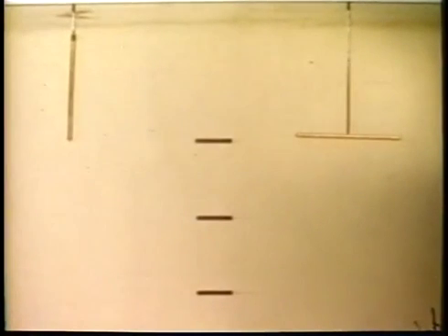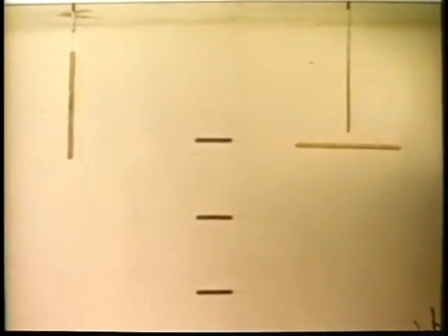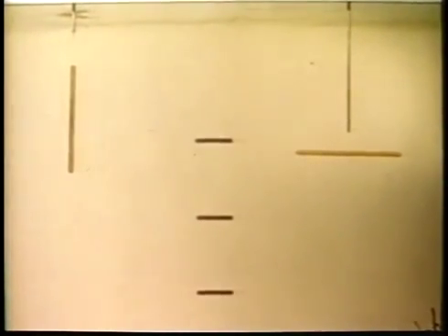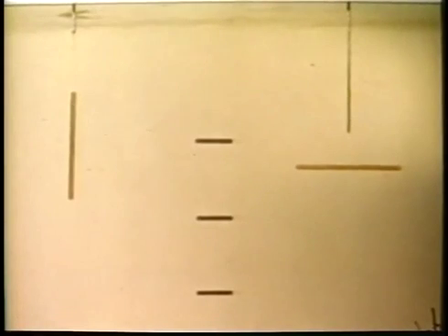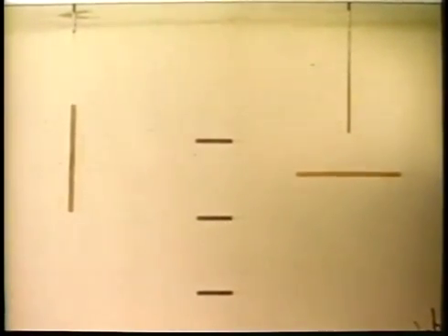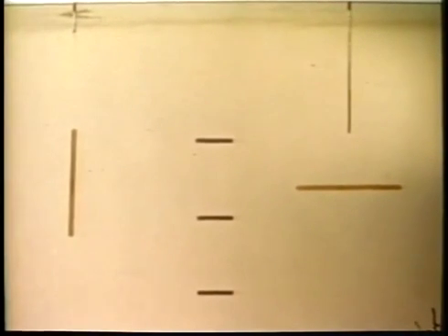At low Reynolds number, they have just half as much resistance to longitudinal motion as they have when moving perpendicular to their axes at the same speed. This is a property common to all long, thin bodies of revolution.